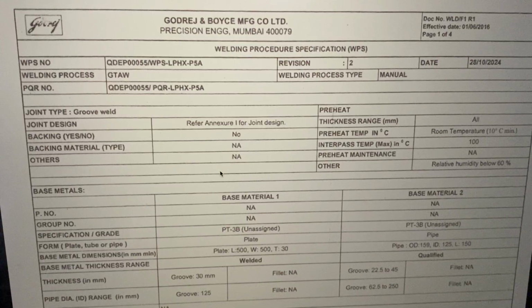Now you will say that this can be seen in a WPQ also, the welder's performance qualification. When we are going to do it, this will be discussed and seen. But especially when impact tests are required, I think it is essential to have backing as an essential variable. Having backing or not having backing, we must re-qualify our process, and also on the type of material.